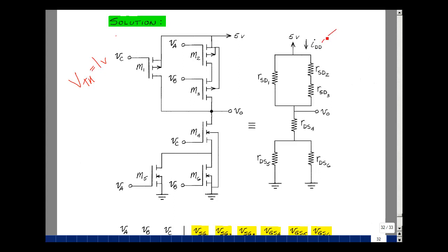Next, I'm going to assume that the current here is small. The reason I'm doing that is that when a transistor has a source-to-gate voltage or a gate-to-source voltage greater than threshold, that transistor could be in the ohmic region or the current saturation region. But if the current going through it is very small, then we're going to be in the ohmic region. That's a trick we used in the Chapter 4 notes. We're going to assume this, and we're going to also show that it's true at the end once we get our final guesses in.